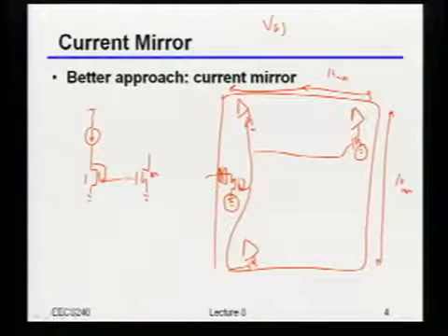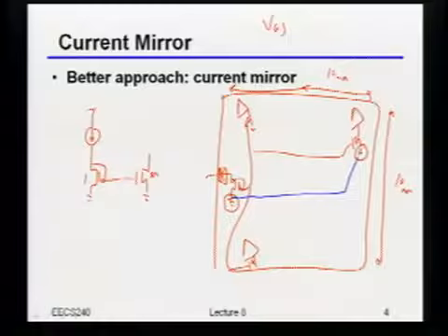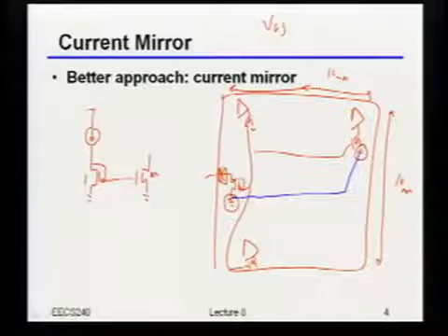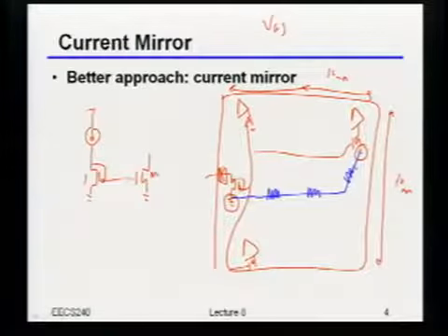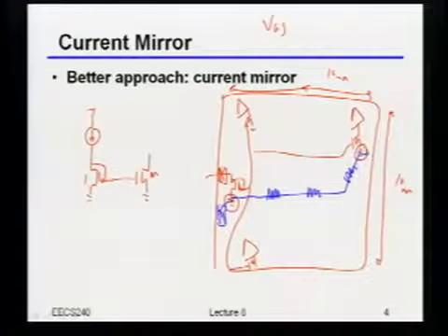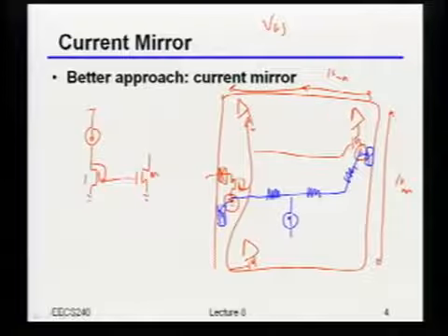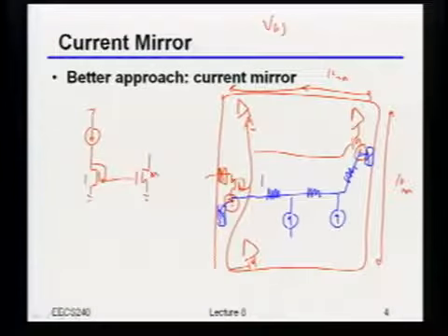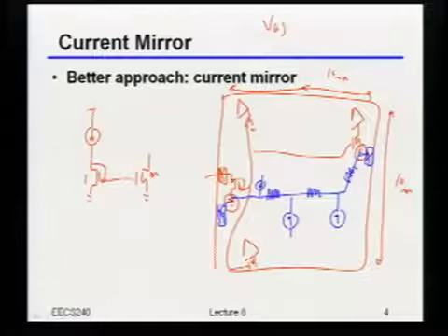It has to span the entire chip. And of course, that ground wire has resistance in it, right? It's going to go out to a pad or something like that on the two sides. But all throughout that chip, I'm going to have other things pushing current through that wire, right?